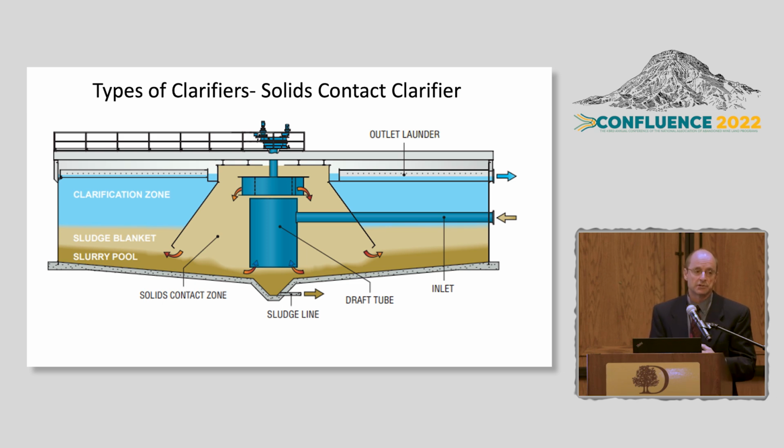So now, just like the previous, in an external reaction tank, you have all of these solids moving around, mixing with the incoming feed. And then when we add the lime, in this case, we have that exact reaction that we had before in the external reaction tank. So you get the precipitation onto these particles.